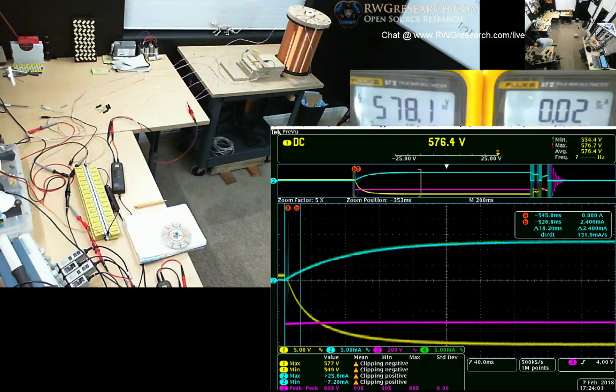But that's not going to give you enough space between the segments. You're going to have to remove 2 or 3 or 4 of them. It must be an even amount, sure. When finished, you should have an insulating non-conducting gap between each conducting segment, which is between 1/8 and a half the length of one of the conducting segments.